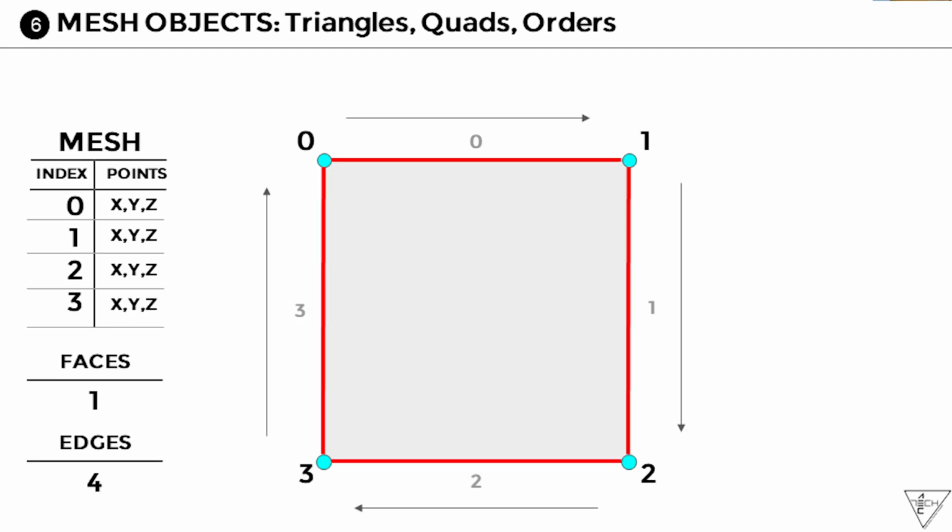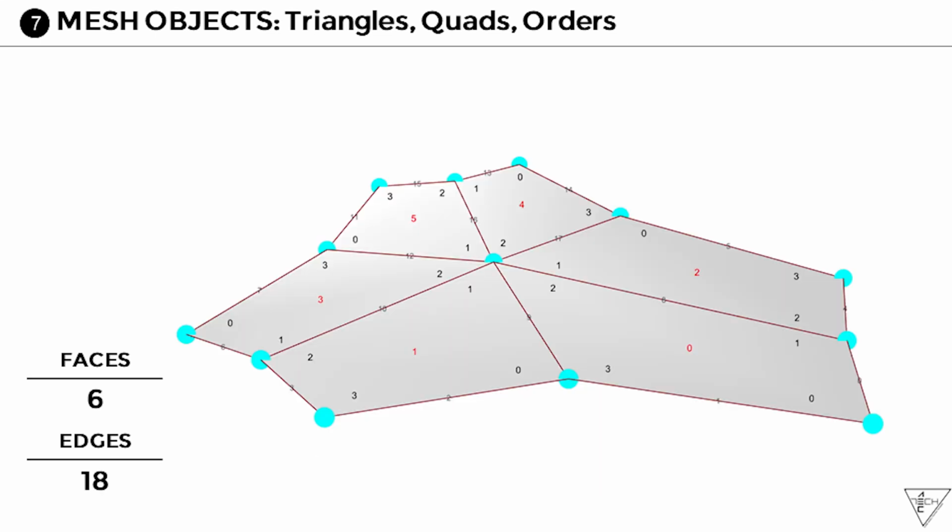and that kind of mentality starts to continue. And that's also the way that most computers construct physical meshes, and as you see in your modeling applications, in this case, Rhino. We're looking at that order and how that order can communicate across. Now, if you take that particular concept and apply it on a given object, you can see the order following through. So you have 0, 1, 2, 3 on this one, the mesh face 1, and then that logic goes across, where it goes 0, 1, 2, 3, and it keeps running across.